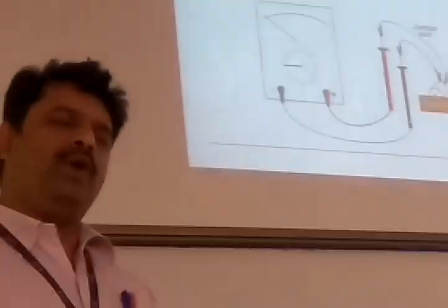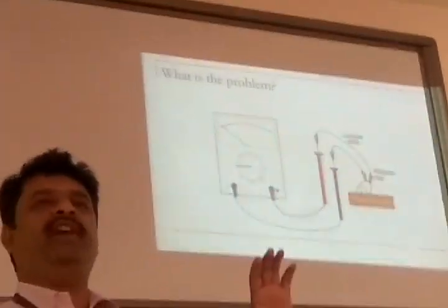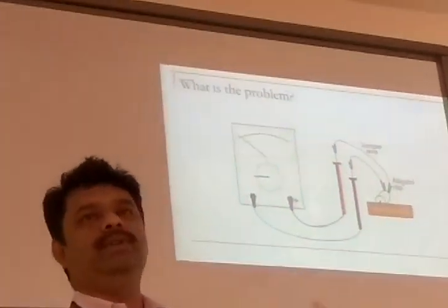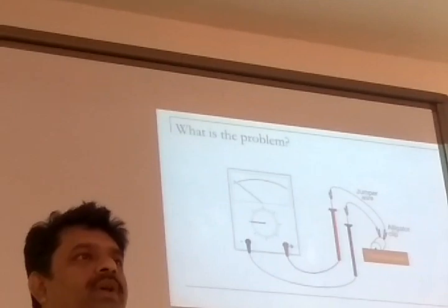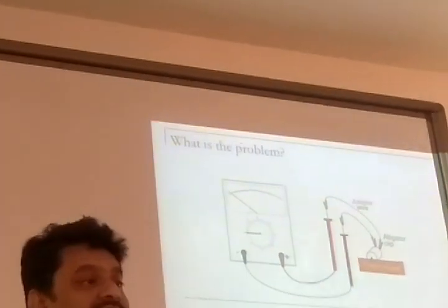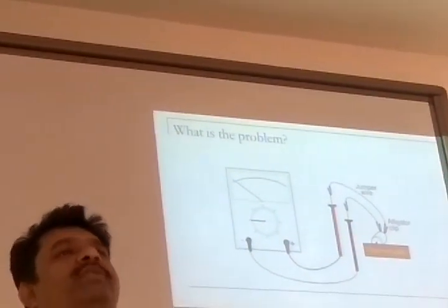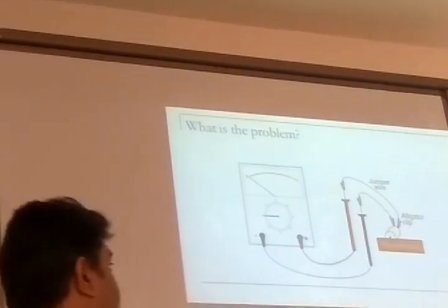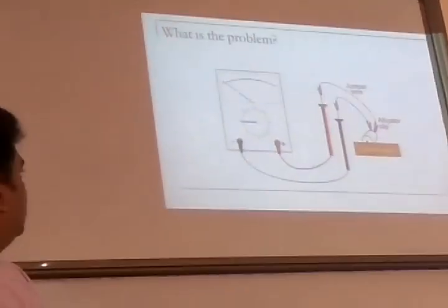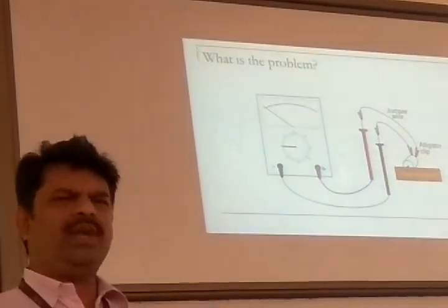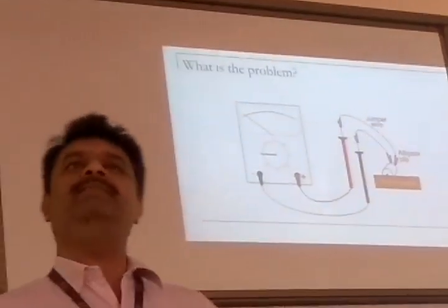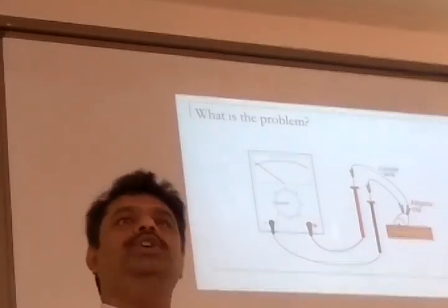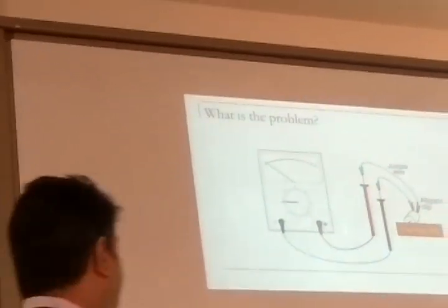So if I have some device which will amplify the magnitude of the signal, then probably I will be able to easily measure. Okay? I want a device which will amplify the signal. That's why the amplifier comes into the picture. Okay? The amplification is needed for this signal that comes out of thermocouple. Not only thermocouple, thermocouple I have taken as an example. Any device which gives very, very low signal, low voltage, you need amplification device.